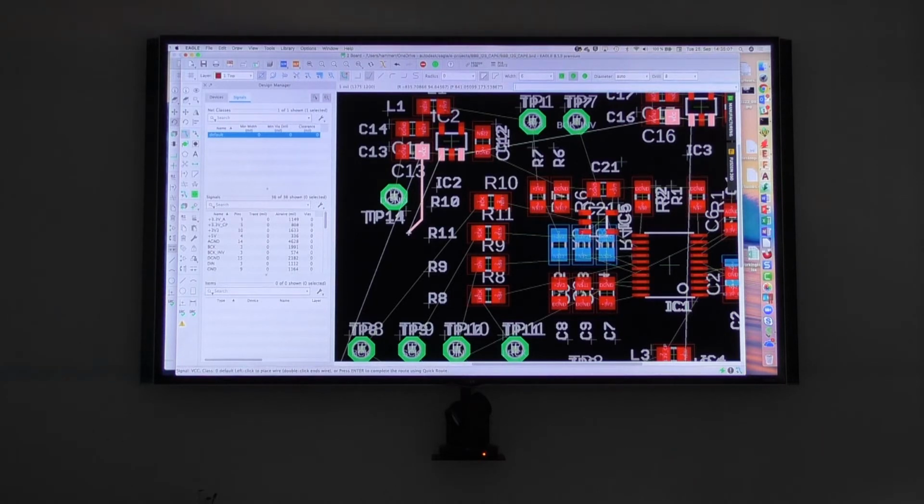Of course you can do this, it's manufacturable, but the bigger the better. If we have enough space to use bigger traces, then we use it, because it's better stability for the board, better connection to the components, better connections to vias, and maybe somebody has to repair such a board because one of the components is no longer working.